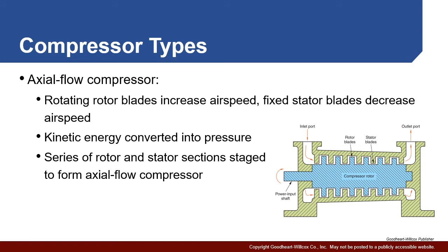So this is capable of much higher pressures, because although each one of these individual stages might not make that much of a pressure difference, a small pressure difference plus a small pressure difference, etc., all the way through here can have a much larger pressure difference. Now, this does, though, rely on kinetic energy. It speeds up the air to produce pressure, and essentially it moves it continuously axially.